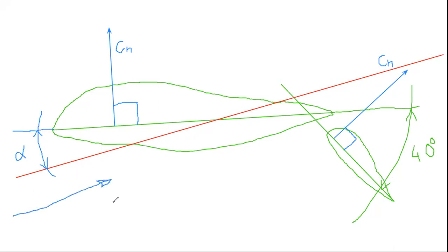This is the airspeed vector. And when we talk about lift, we talk about vectors that are perpendicular to this curve. And we need to find this vector. Also, we could obtain drag coefficients from these values. So we need to transform our data to different coordinate systems. We need to do a rotation of the coordinate system axes.